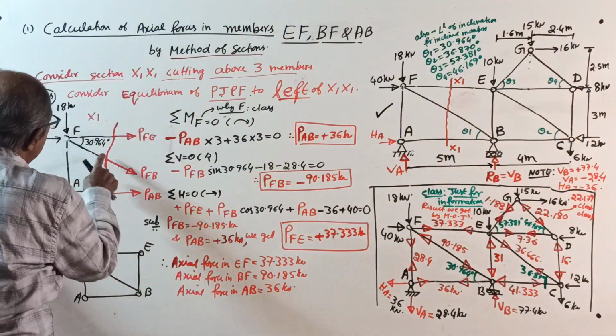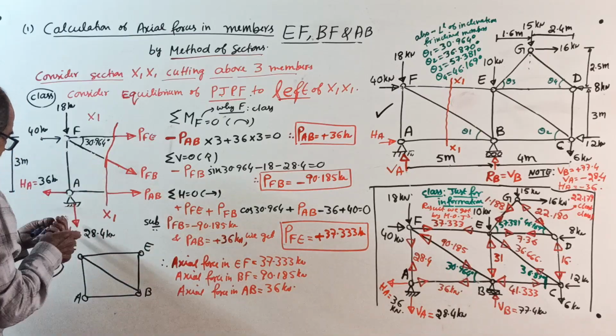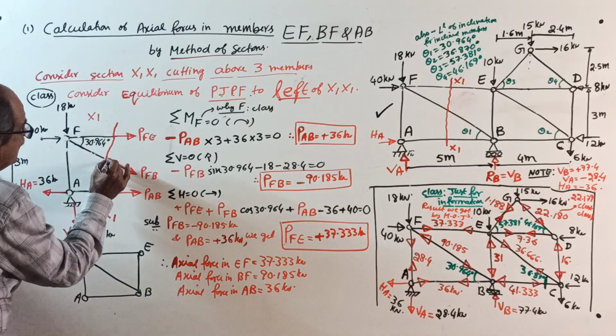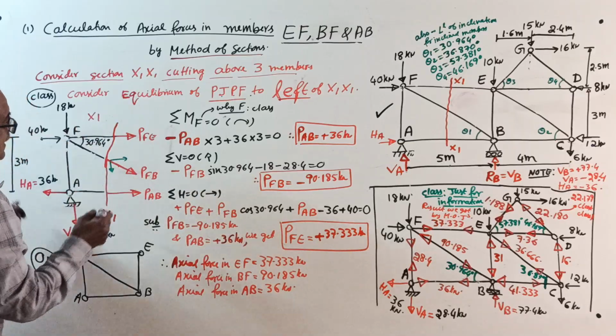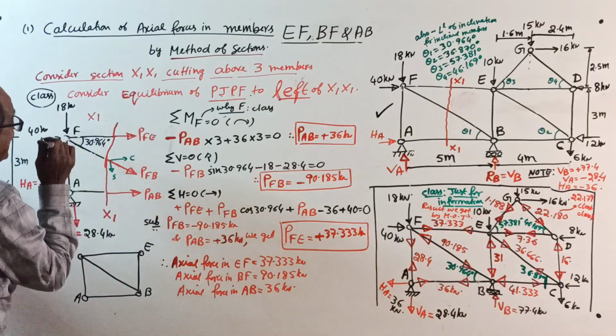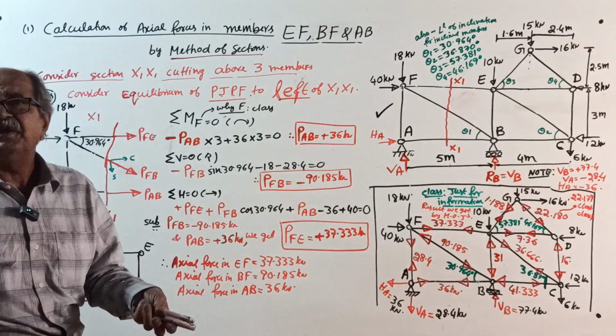This is an inclined member. Okay, now, see, there is an inclined member here. Take a pencil and mark here the right component and down component, for resolution purpose later. Horizontal is cos, vertical is sine with respect to this angle. If this is not clear, you are not fit to study from me.